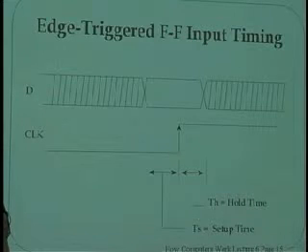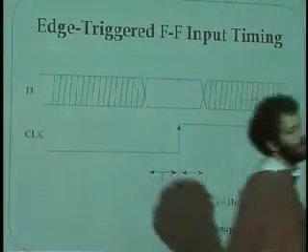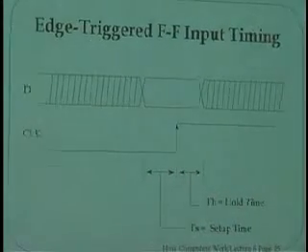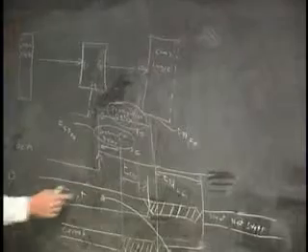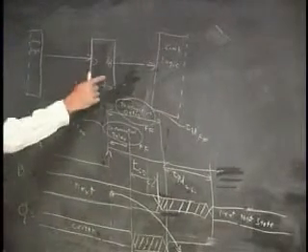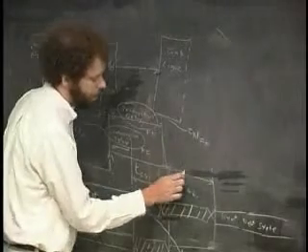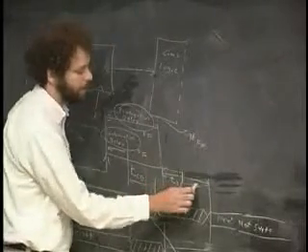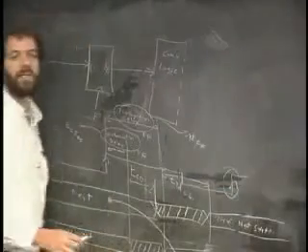But let's first of all talk about this business of taking a picture of the data. It's really great because the questions have led directly to this. When can I next make this clock go from low to high? I know I have to wait till the next state comes out here, because that's coming in on D, and that's the next time that I can tell this thing, take a picture of the next state. I can drop this clock down whenever I want because it doesn't listen to that, but when's the next time that I can make this clock go off again?